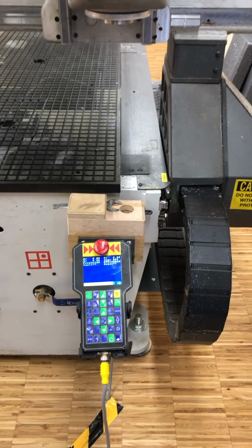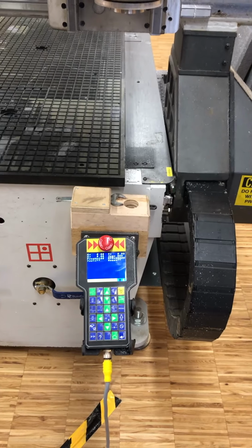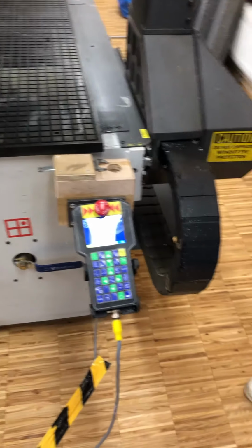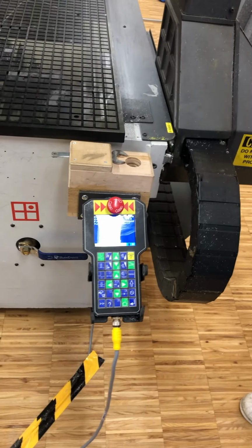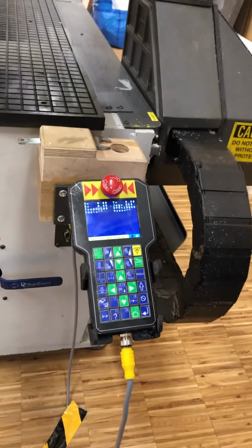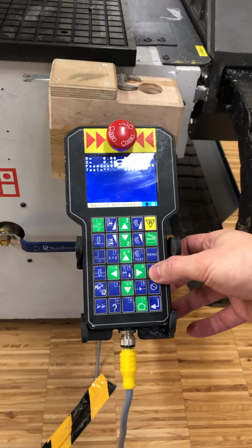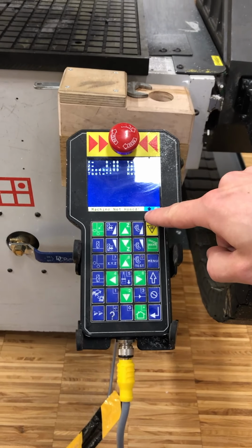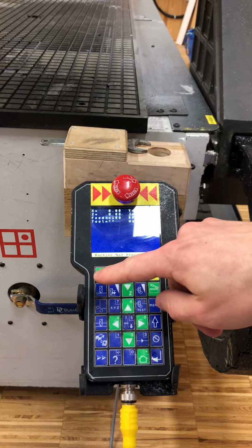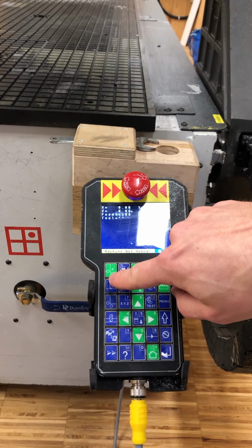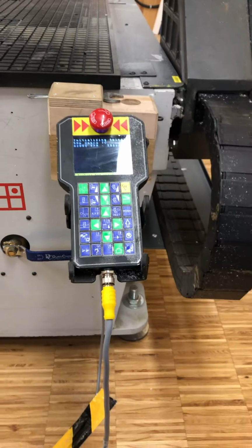But it could be that the y-axis is on the other side, and then it will slowly find its home. So now it will not be the best circumstance for demonstration. To allow the machine to locate its hard home, press the blue shift key here, and you can see on the controller that the shift icon lights up, and that makes sure that you can hard home with the hard home button here to the upper left. So now it's going to home.